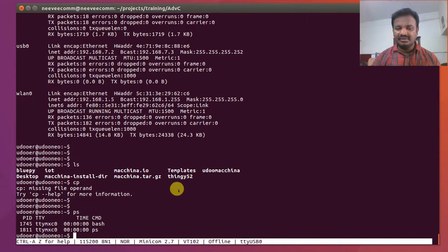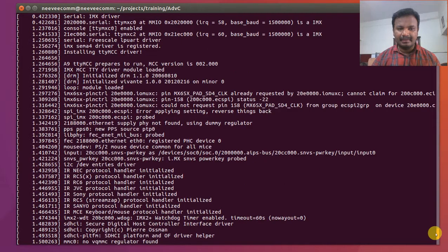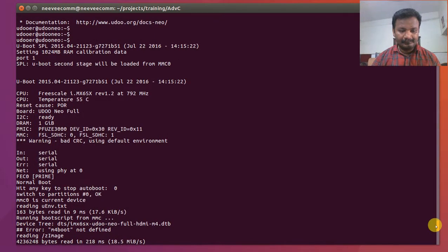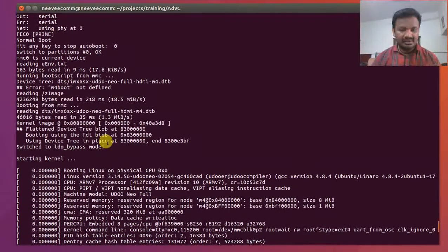When we compress, maybe we can see here how the extraction is happening. Here we have something like a zImage. This is a gzip-based image that has been loaded. Once we give it, it will extract the kernel image and then start loading. Basically, that extraction is taken care of by U-Boot, so the kernel image can be compressed, as our embedded devices have limited storage. We cannot put the vmlinux directly; we have to compress the Linux image.